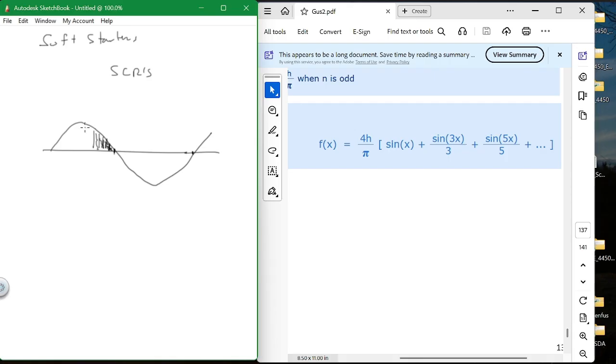But basically, all it can do is, at some point in your sine wave, it turns on. And then when it goes through zero, it turns off. It comes back here, turns on, and then it turns off when it goes through here. That's all it is. SCRs. They're big power. You can use them for high power, but all they do is allow you to ramp up your speed. They do not control your speed. So once you get up to full speed, they're useless. Okay? They don't control your speed.